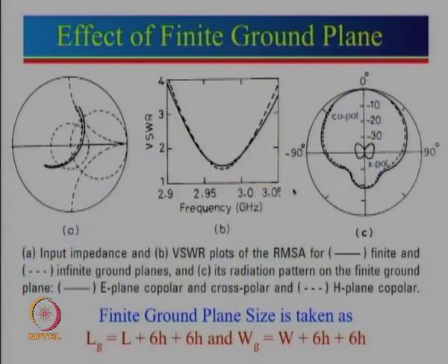So, when we were studying these effects, we looked at what is happening to the ground plane, and the moment we started reducing the ground plane size, we could see that just a single patch is radiating equally. That means if you take L equal to Lg, you can design a very simple bidirectional antenna. Remember, there is a disadvantage: because it is now radiating in the front as well as in the back, the overall gain reduces. But that is the property of the bidirectional antenna.